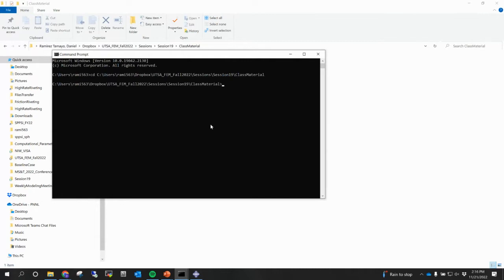And then I'm gonna enter the Abaqus command. So whenever you hit submit in Abaqus, you're just typing this: Abaqus job plate course, CPUs, let's run with 16 CPUs, interactive job, and that should be it. Let's run it.